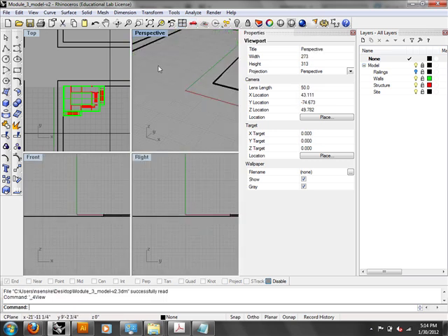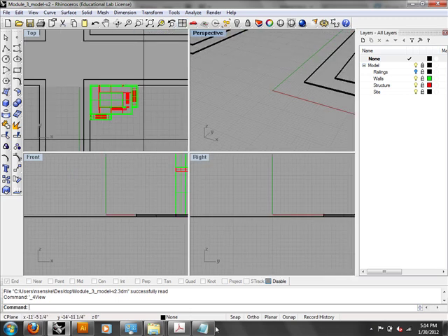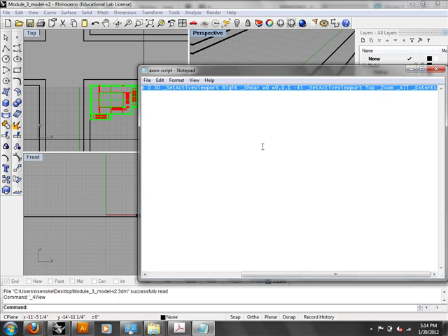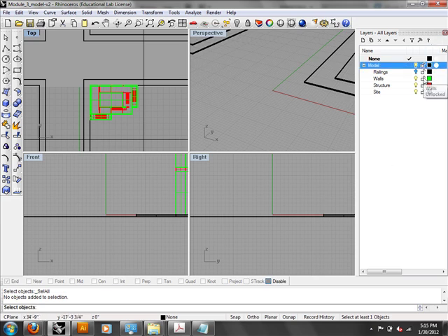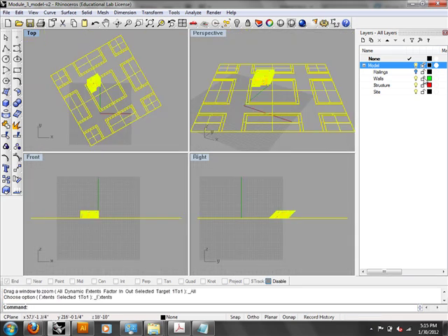It's important to start it off in the quad view, and I'll have this written out. So 4 views, and then I have my script file that we're going to give you guys on Moodle, and you're going to select everything and copy it, and then you're going to be in the top view. You're going to paste it into your window. So Control D, select objects, fine, select all. Oh, I have to unlock my layers. And then you run the script.